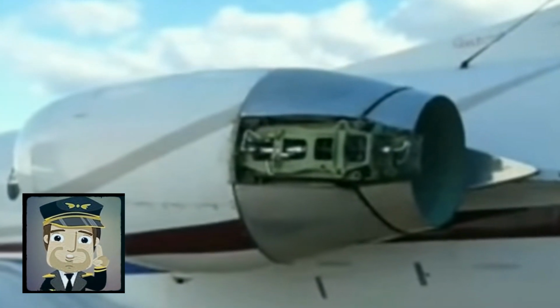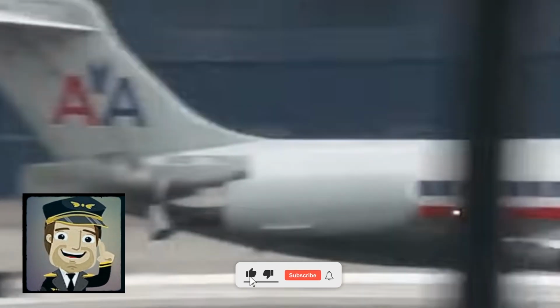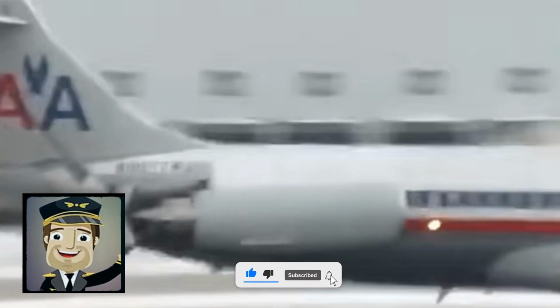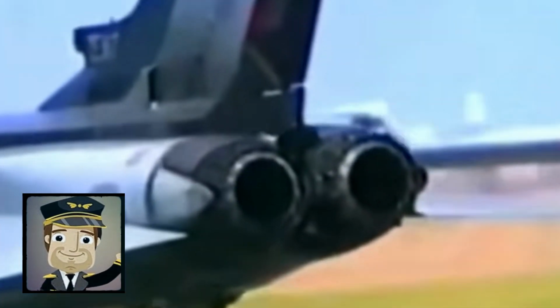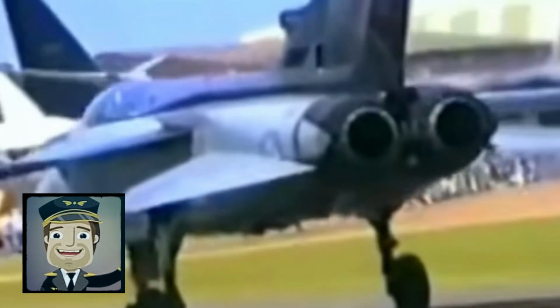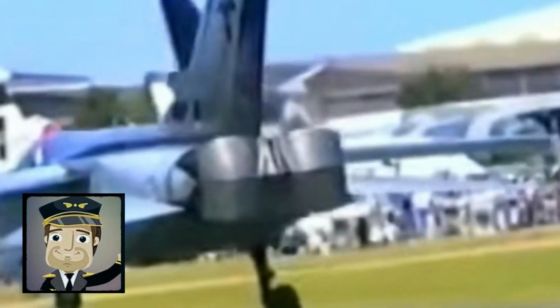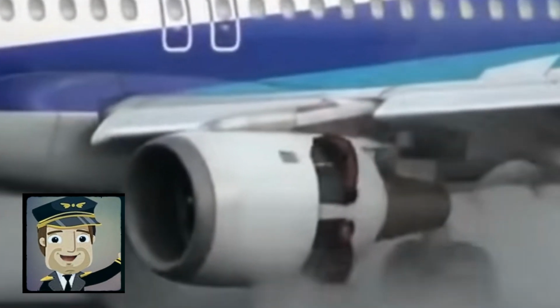serious accidents. From a technical standpoint, the actuation of thrust reversers can be hydraulic, pneumatic, or electric, depending on the aircraft design. For example, Airbus A320 family aircraft use pneumatically actuated reversers powered by engine bleed air. Boeing's 737 aircraft use hydraulic systems. More recent designs, such as the Airbus A350, use electric actuation, which reduces system weight and mechanical complexity.